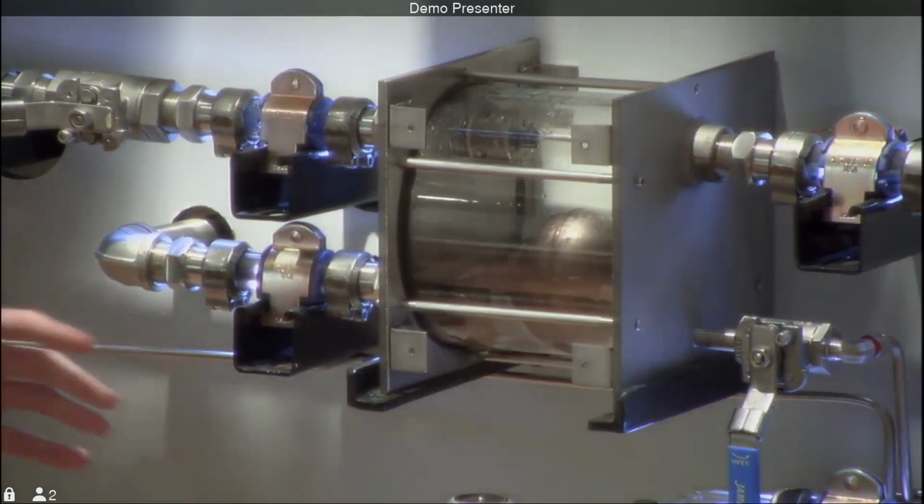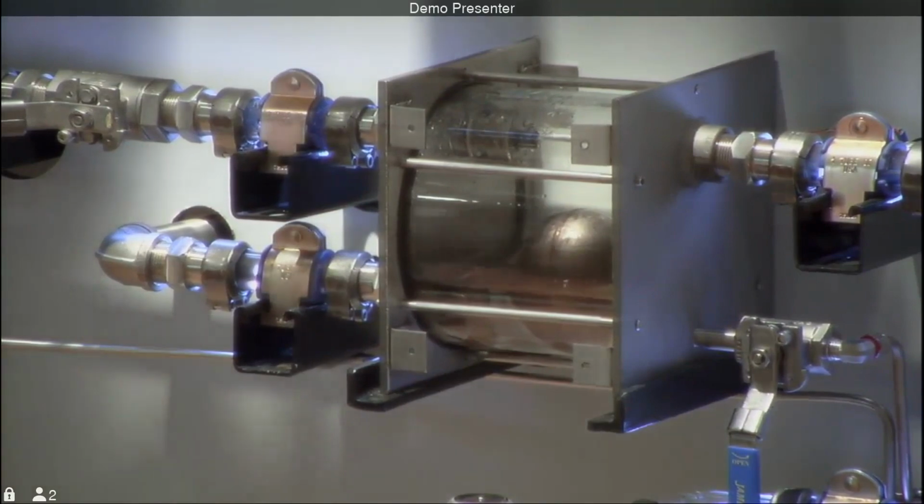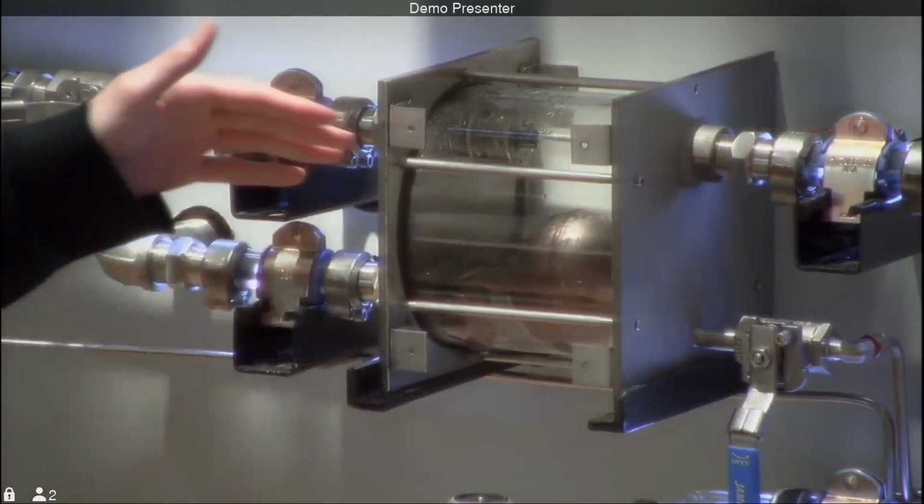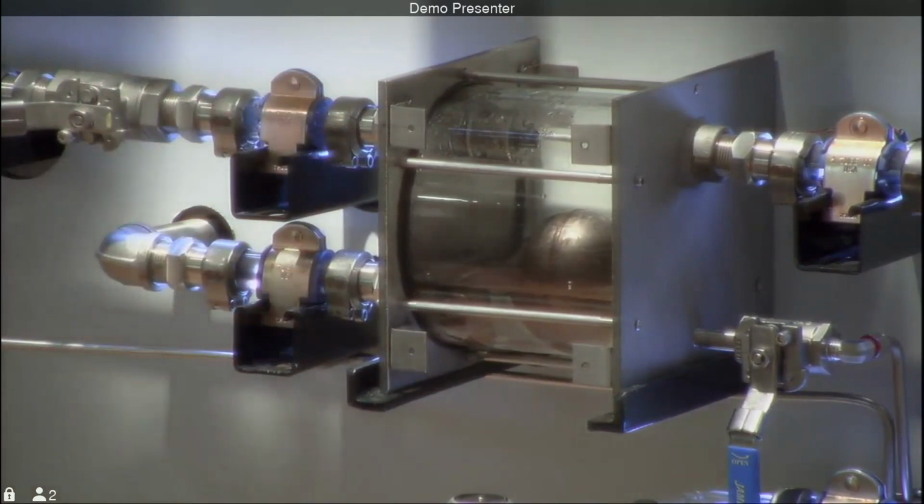Some of the main advantages of this trap are that it handles modulating pressures and varying loads very well, which is why it's our #1 recommended trap for heat exchanger applications, or really any application that has a modulating control valve. It also handles quite a bit of air too, because it has its own dedicated air vents as well.